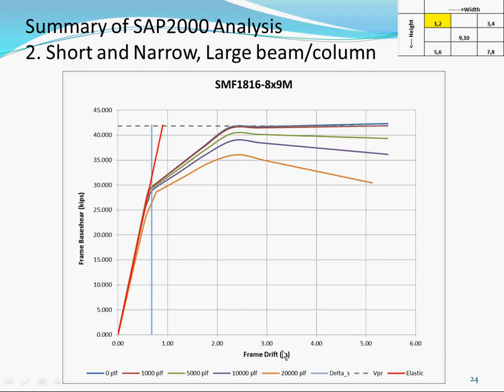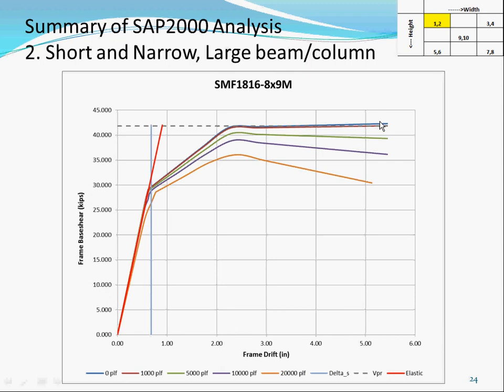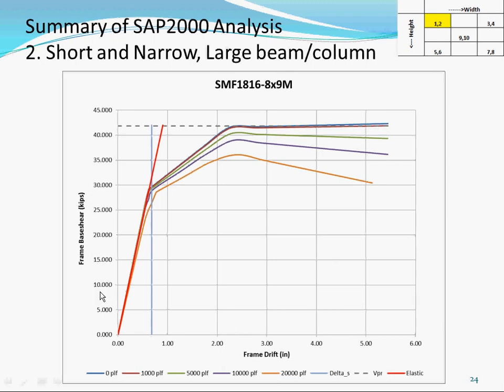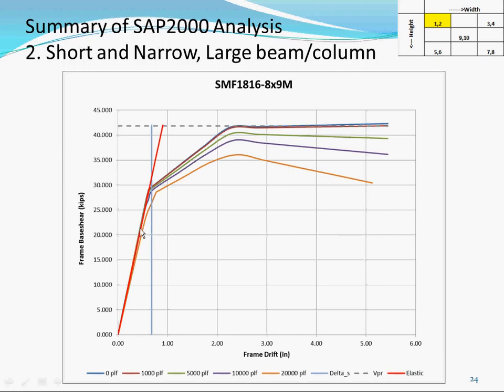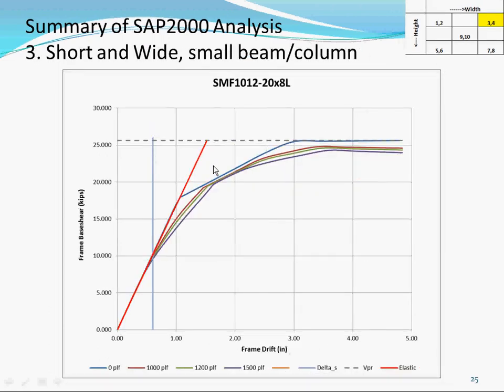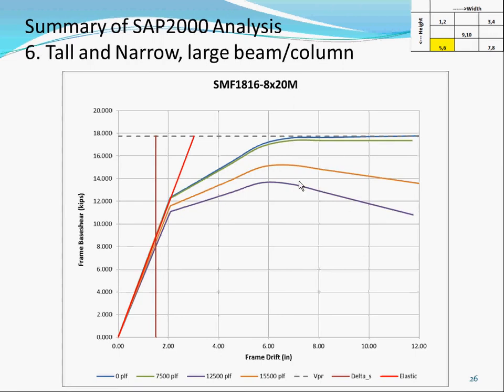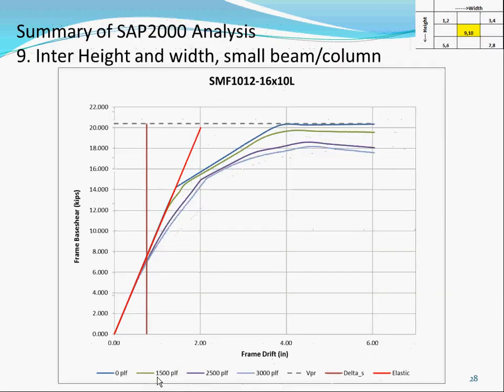When you push over without any gravity load, you get the top curve. With whatever gravity load, not even maximum, you get a lower curve, and also you get a little P delta. That's where the P delta comes in, because you're adding a lot of gravity load. It's starting to tip over, so you can see the difference. We did a lot of study on making sure the design is elastic, and we don't go into the inelastic region. So that's all the analysis checked before. You can see this P delta is very significant when you get to 20 kips per linear foot. That's like 15,000 pounds per foot. That's a lot. So that's why these are just analysis.